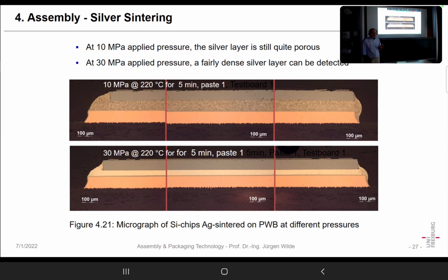The dissipated power is not the electrical power we have in that device, but the power that is lost due to efficiency losses. So ohmic losses in the device will lead to self-heating, and the thermal resistance gives us the temperature increase per every watt of lost power in that chip.